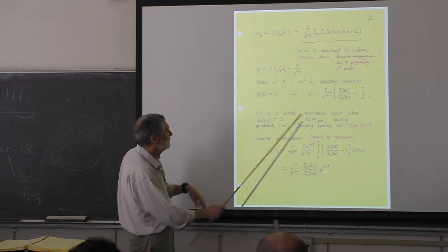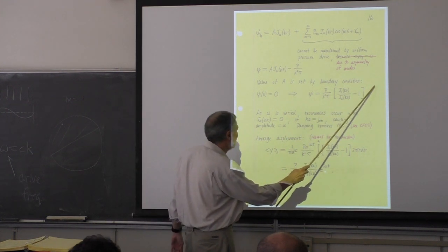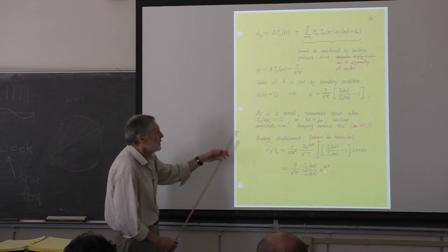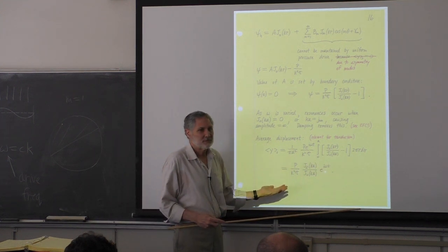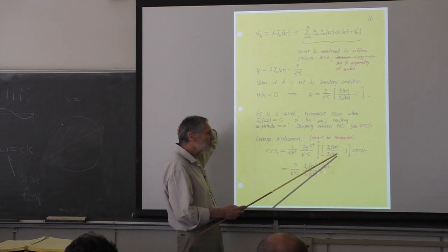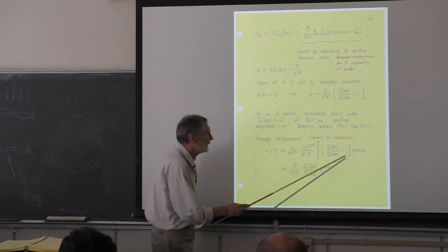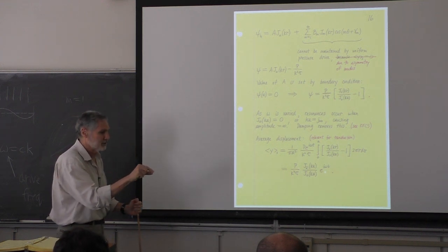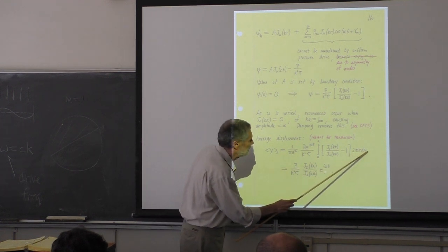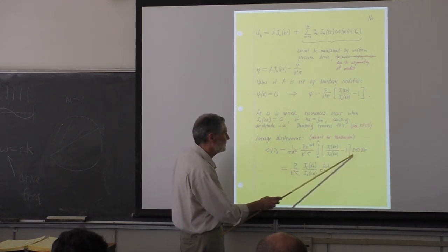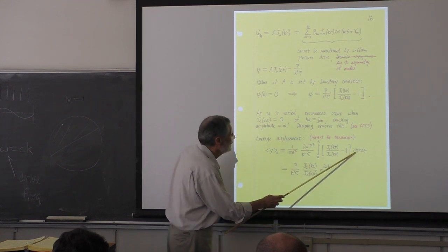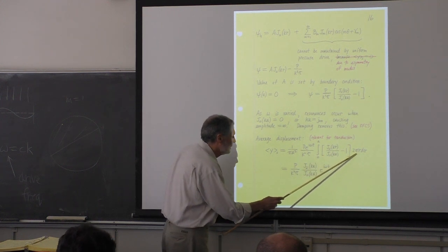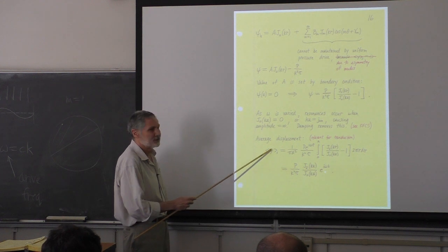We have our y. We would just multiply this by e to the i omega t, and then we need to multiply this by, we went through this yesterday. We need to find the average. We multiply by a little amount of area, and because of this axial symmetry, we're just going to take a little strip here, the 2 pi r dr, because all the y's, the displacement, is the same along that, for that analysis. So we take our displacement multiplied by the area, integrate, and then divide by the total area. That's going to give us the average y.